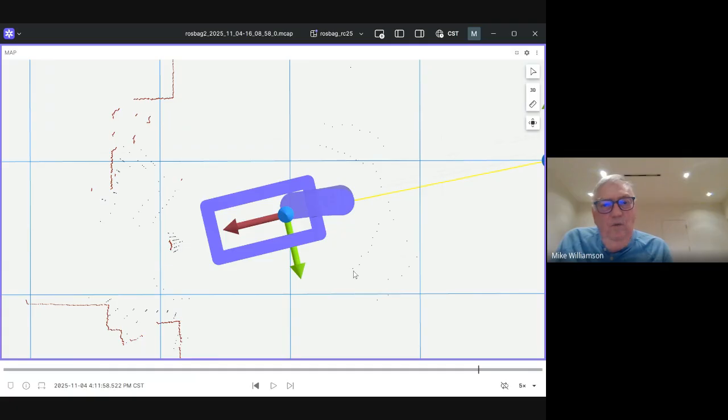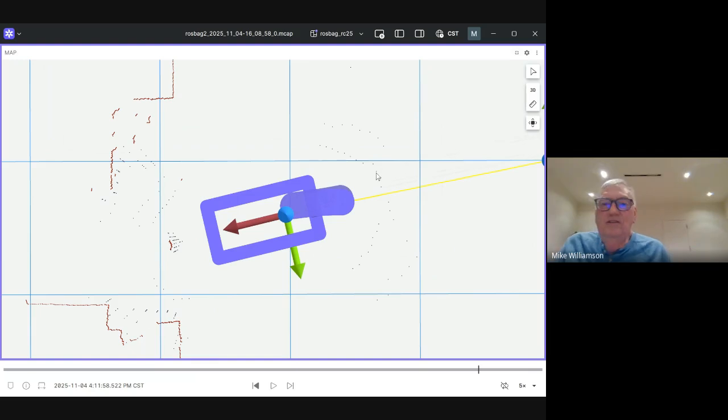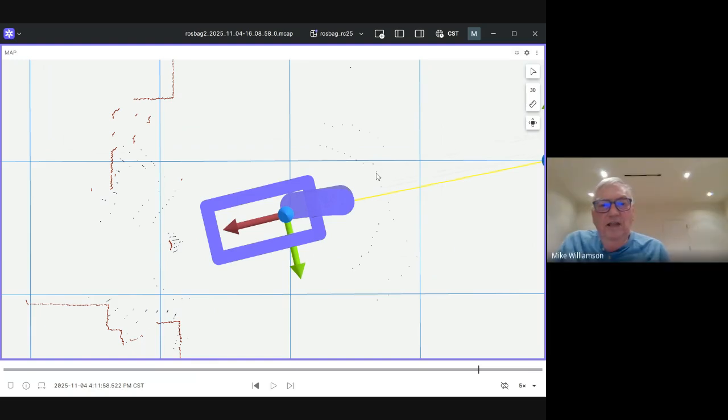And when I compute that into a point cloud, these are at zero meters above the floor, and I ignore any of these points below 100 millimeters, 10 centimeters, just so that I don't count those as obstacles to avoid. So I'm not trying to avoid the floor.